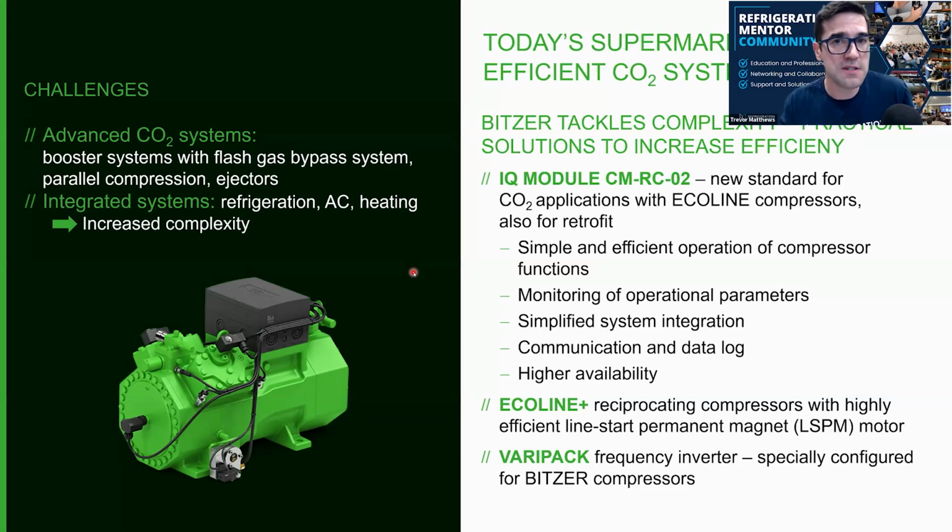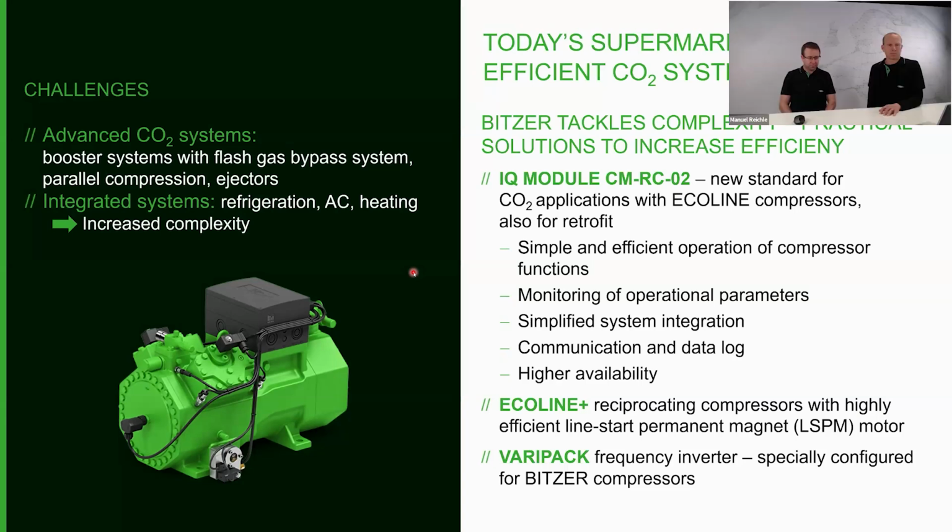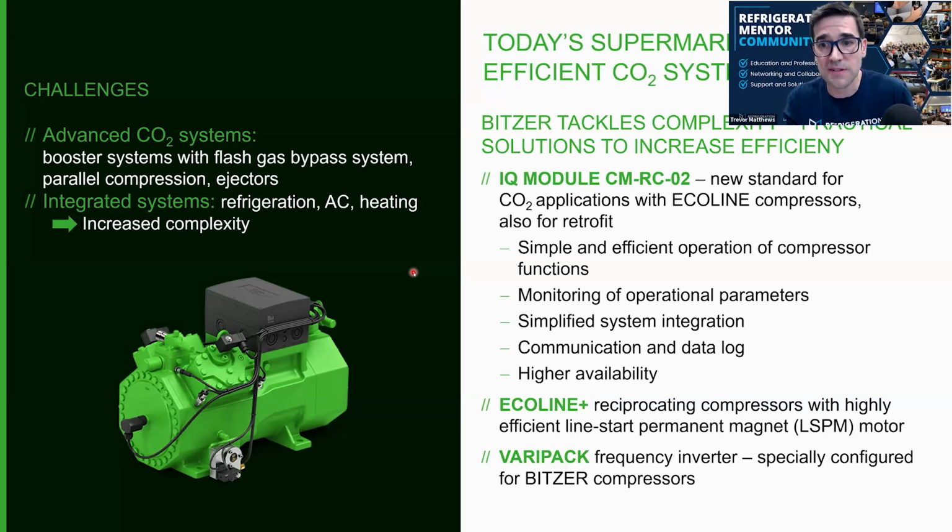But when I first started learning CO2, no one really talked about the issues in low load situations. Now I'm seeing more and more of that being an issue, where all of a sudden it's minus 40 or minus 30 out, and systems are running into more problems. And then you just said it, you got curtains pulled down, it's the middle of the night, everything is satisfied. This is where capacity control comes in huge.